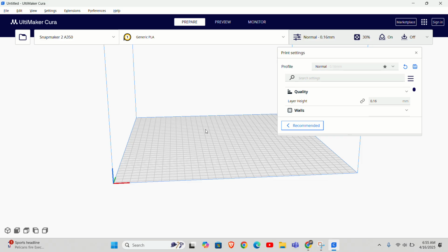The machine gets commands like x axis, y axis, and z axis. For example, at x axis 25 coordinates, the machine will move accordingly, and you will get your 3D print. This is called a G code file. So in Fusion we get the STL file, and I'll explain in detail in this lecture how we get from STL to G code.